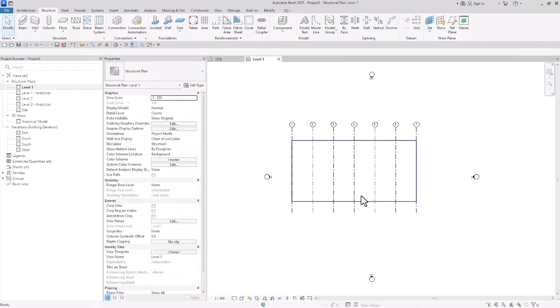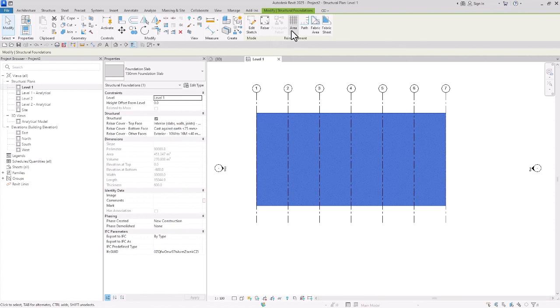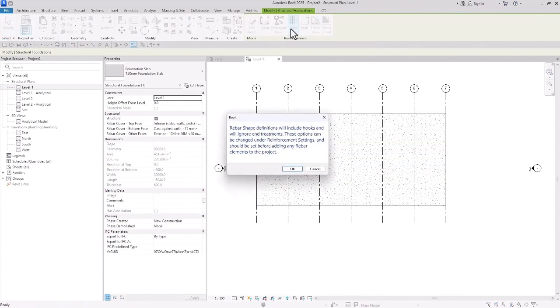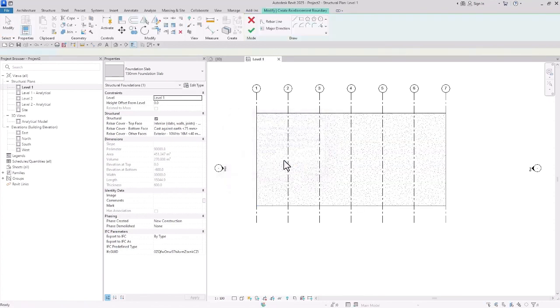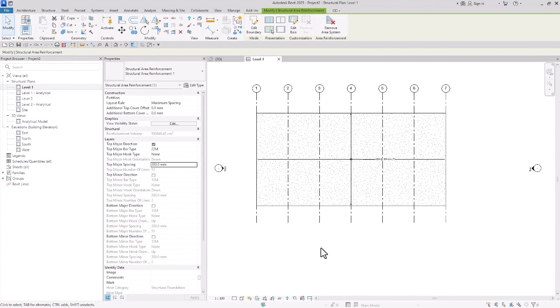I'm going to remove those symbols for now. Now, select, and then from area, although I said this doesn't support area, I'm just going to use this because I'm trying to work faster. And after that, we can actually use remove system. Just want to consider the top part here with rebar number 22. 300 of spacing is good.